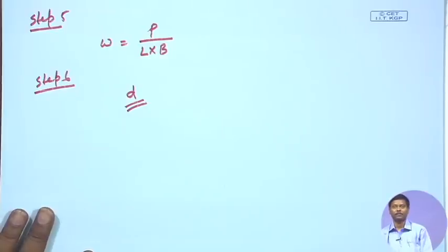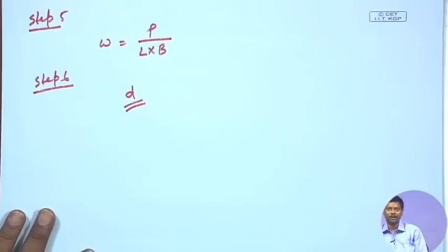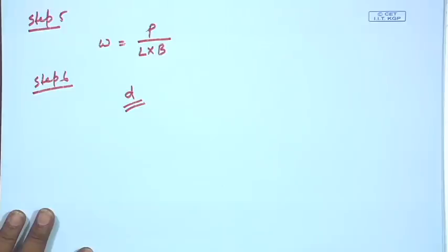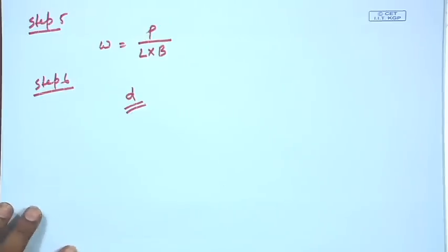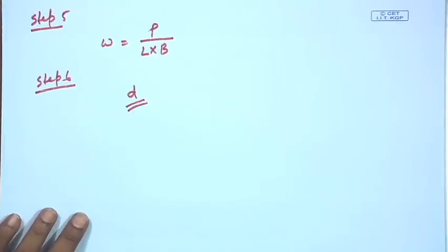The depth of the critical section will be the total depth, which includes the depth of the base plate and the thickness of the horizontal angle, if the connection is bolted. If it is a welded connection, then the required thickness that comes out will be the thickness of the base plate.